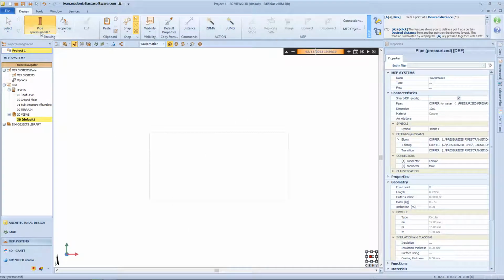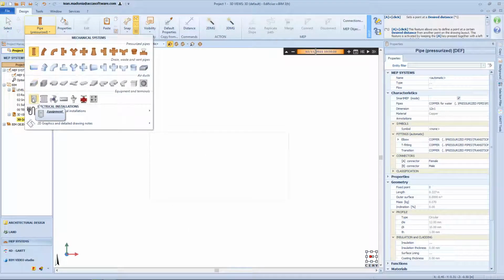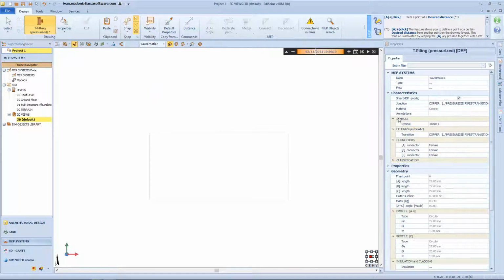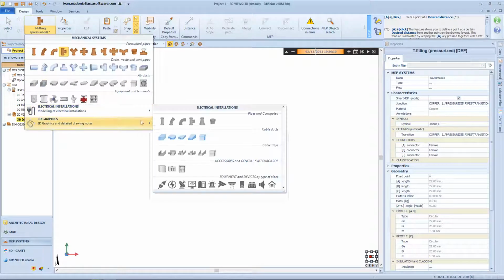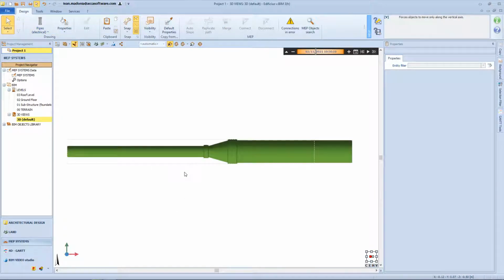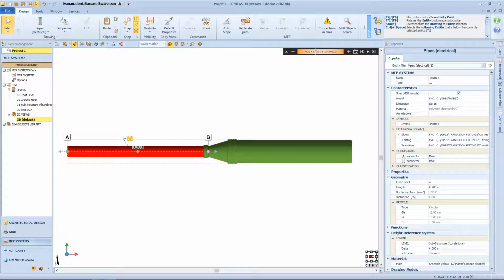If you activate a pipe, a corrugated pipe or a fitting from the drawing menu, the Transition Joint option also appears in the Properties toolbox. It is automatically generated with the Smart M.E.P mode when two M.E.P entities are connected and have coincident axes and profiles that may even differ in shape and/or size. The Transition, automatic connection, acquires, in correspondence with the connection, A and B, the shape and size of the profile of the M.E.P entity from which it is generated.